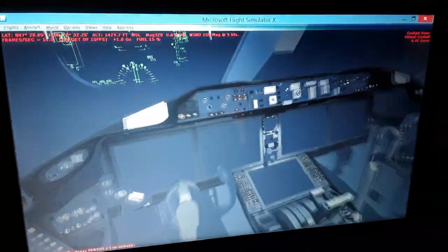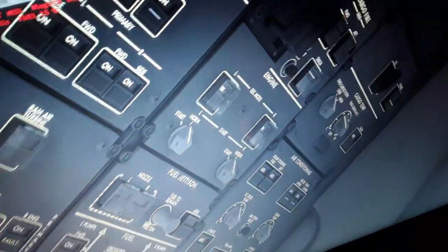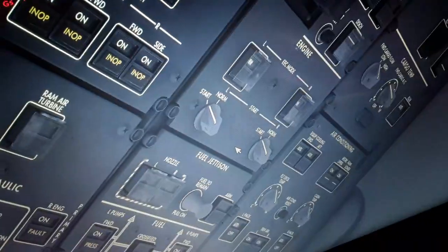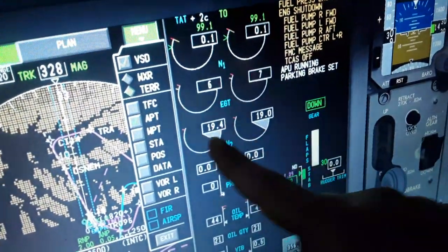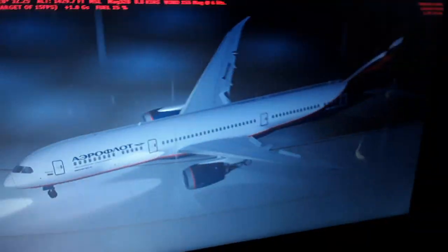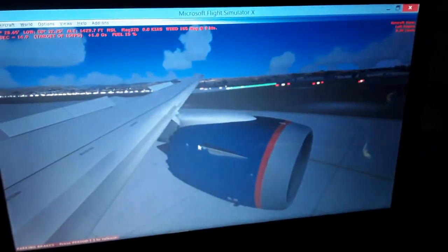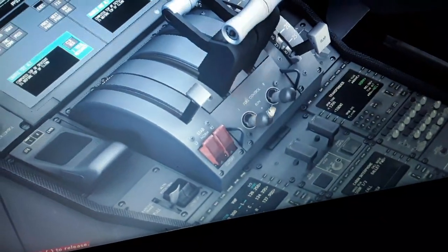So we're going to restart them. Over here in the overhead panel you can see left and right engine autostart in the start position. Also it illuminates the switches with an amber color. So we have the low pressure compressor turbine and the low speed spool. Only the high pressure compressor turbine here has pressurized air admitted for the engines started right now from the APU. So we can let the fuel control, fuel valves both on, left and right engine on.